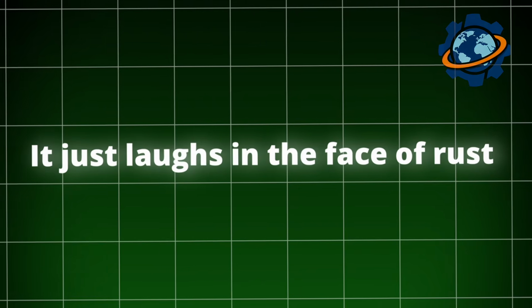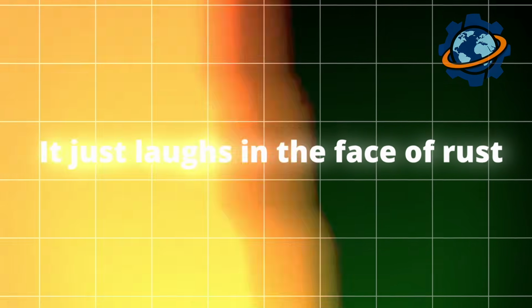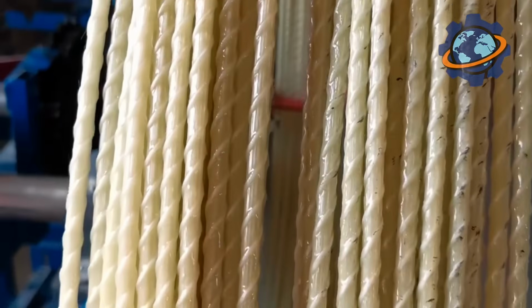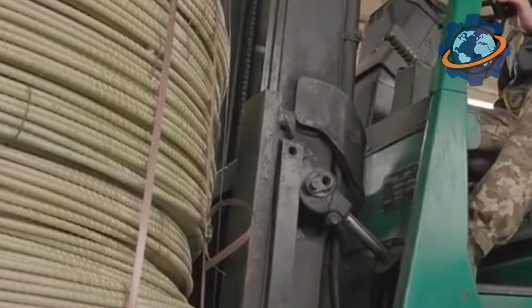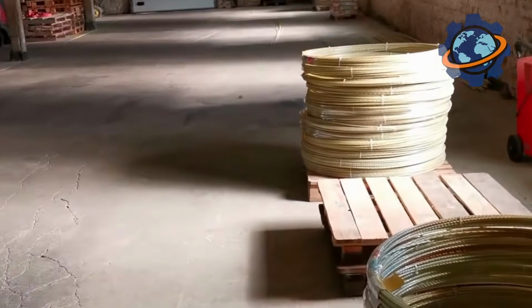And fiberglass? It just laughs in the face of rust. It is chemically inert. It is completely indifferent to water, salt, acids, and alkalis. This means that the service life of the structure increases dramatically. A concrete structure reinforced with steel is designed for more than 50 years. And a structure with fiberglass rebar is easily designed for more than 100 years.